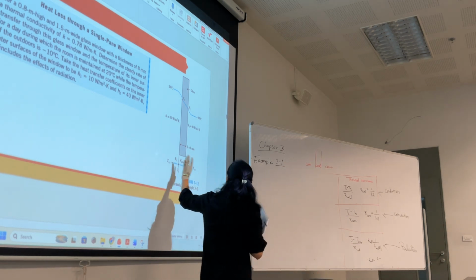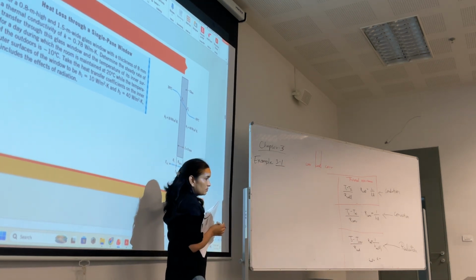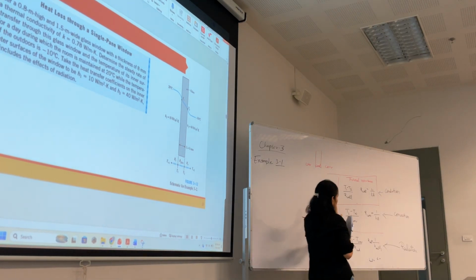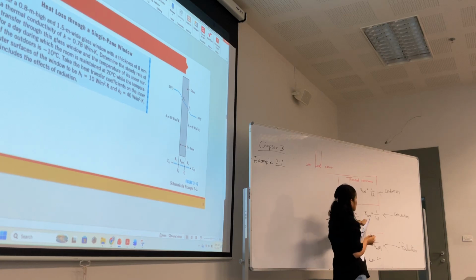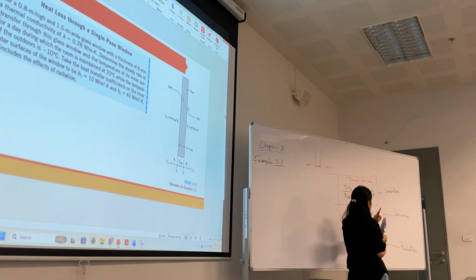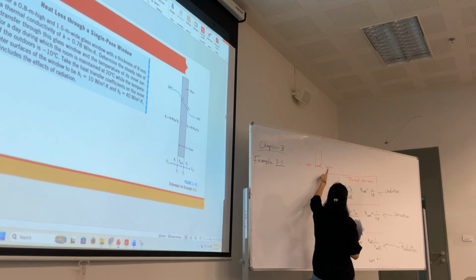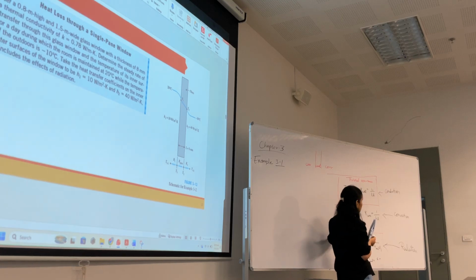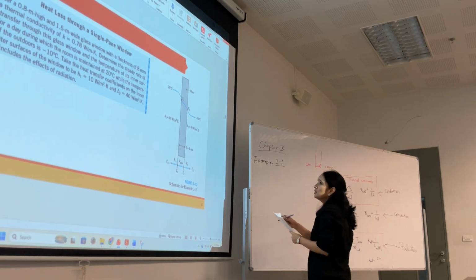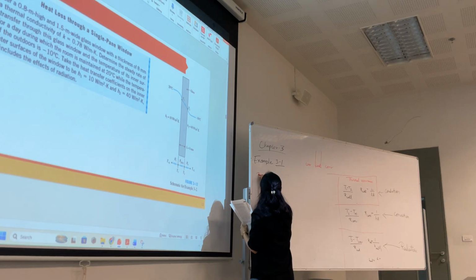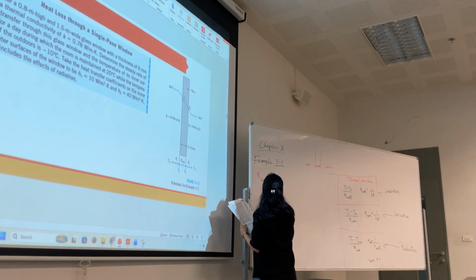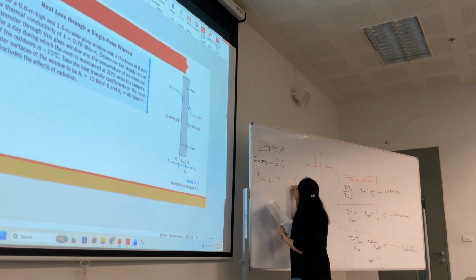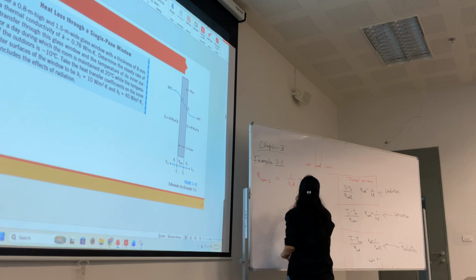Heat transfer will be happening by convection, conduction, convection. So we are going to use the thermal resistance method. First we can calculate R. We need 2 R convection and 1 R conduction, and then we will input them here. So first let's calculate R1. Okay, we'll use H1.